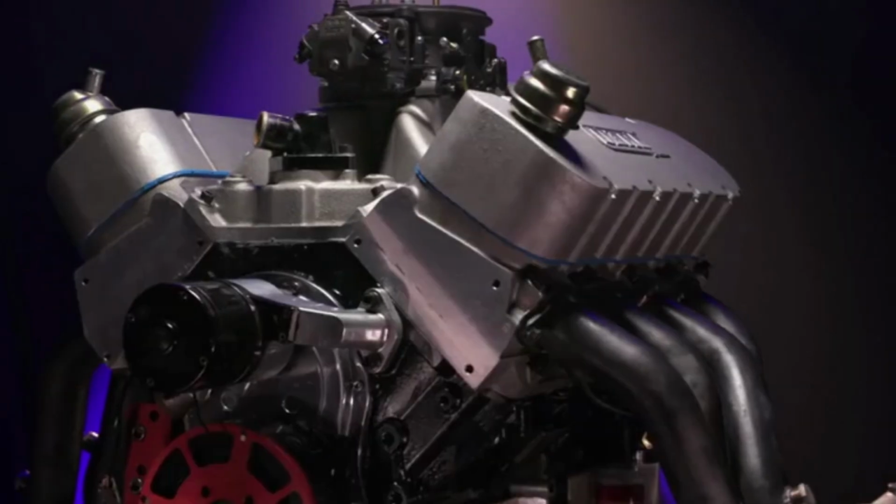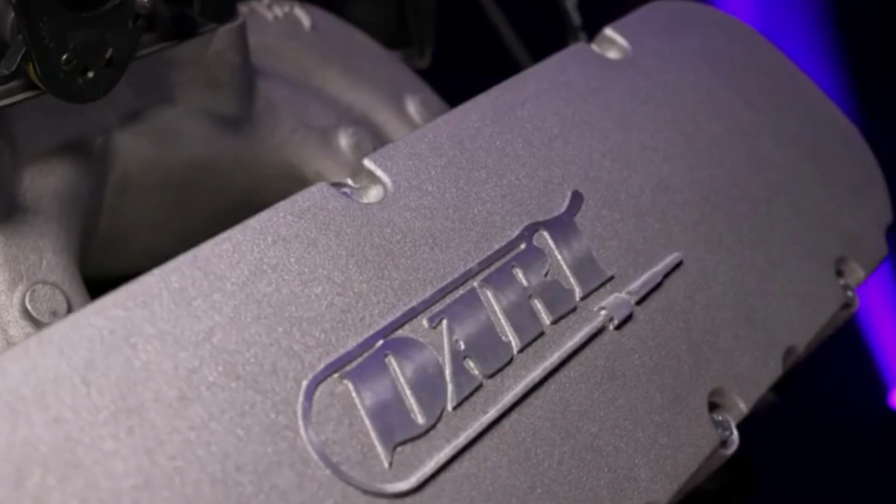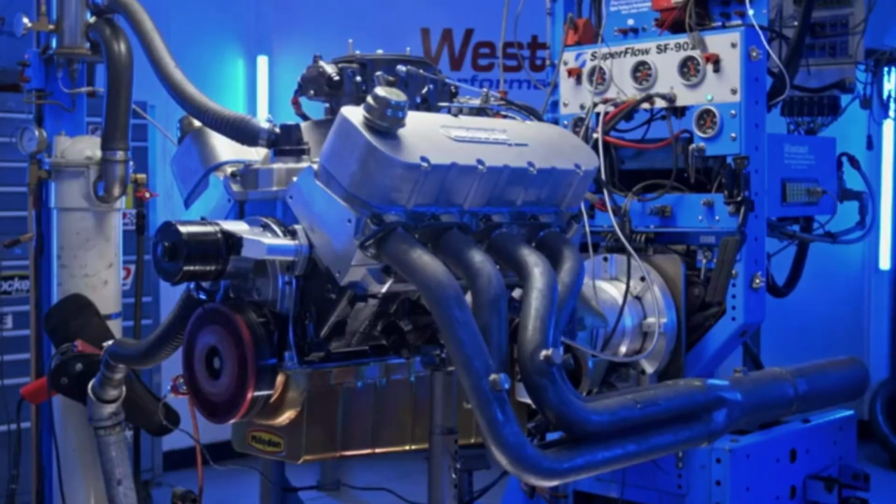So Steve has got this thing completely tuned up. He's handled the carburetor calibration. He's done a timing sweep on the thing and found out that it's insensitive between 34 and 38 degrees total. It's the same. Yeah. So we've got it at 38 degrees, and when we do the other engine, we'll do that same timing sweep. And as a matter of fact, I think we'll look at the fuel curve also. So with the knowledge that this is ready to go, fire it up and let's do it. All right, here we go with the long rod engine. 6.800 is the length on these connecting rods.